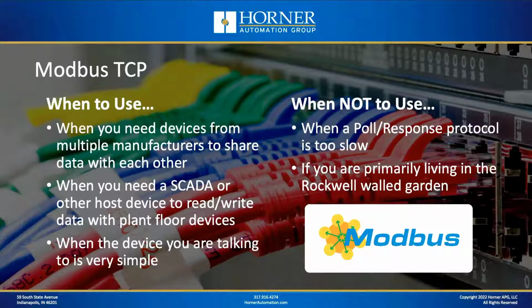All right, now we're going to talk about when to use and when not to use these different protocols. Just to give you some hints. So first of all, when should you use Modbus TCP? If you're looking to have devices from multiple manufacturers communicate with each other, Modbus is a great protocol. It's probably the best one out there.